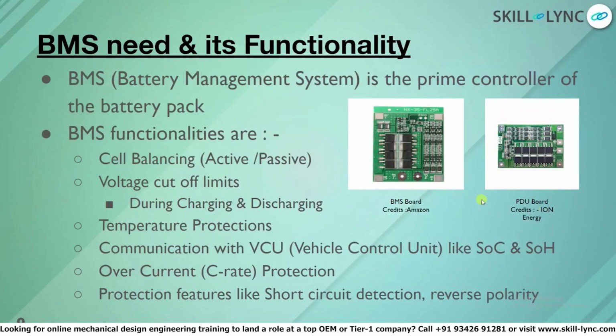So the next slide is about the BMS need and its functionality. So what is the BMS? BMS is the battery management system, and it is the most important, main control authority of the battery pack, responsible for safe monitoring and safe functioning of the battery pack. The major functionalities are cell monitoring and cell balancing, which is one of the major tasks of the BMS, where it monitors to keep all the cell voltages uniform throughout the operation of the battery pack. We also discussed voltage cutoff limits during charging and discharging.